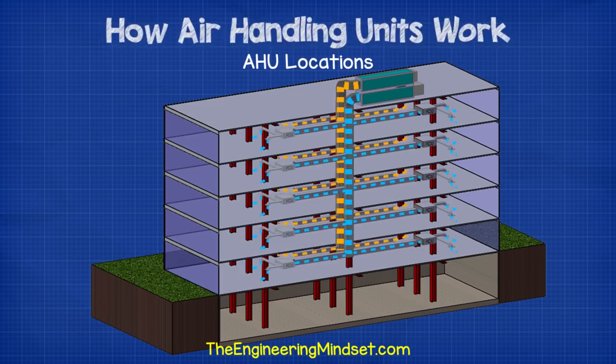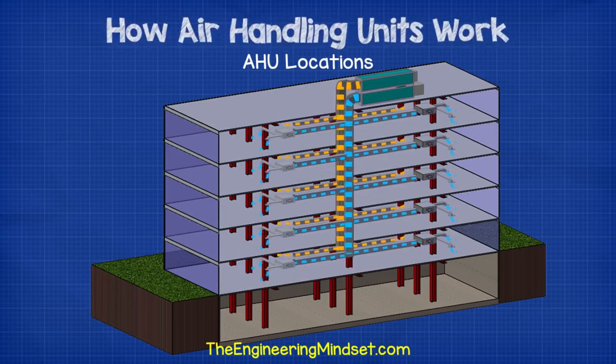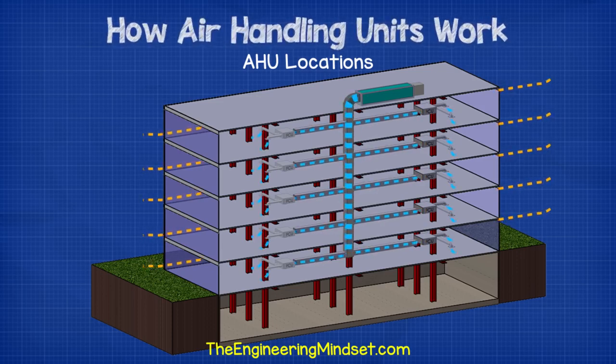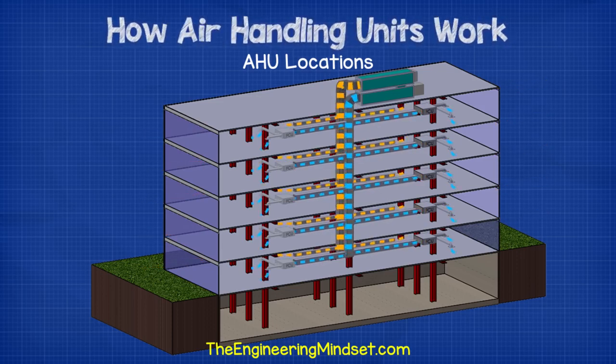Some buildings, particularly old high-rise buildings, will have just one large AHU, which is usually located on the roof. These will supply the entire building. They might not have a return duct. Some older designs rely on the air just simply leaking out of the building. But this design is not so common anymore in new buildings because it's very inefficient.